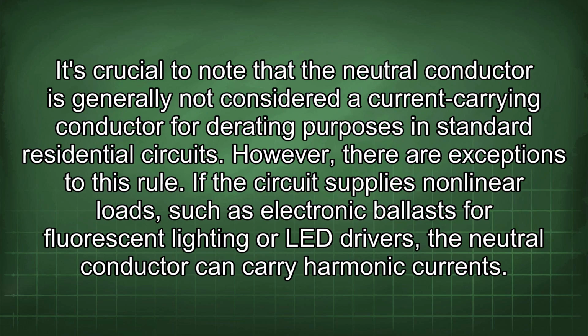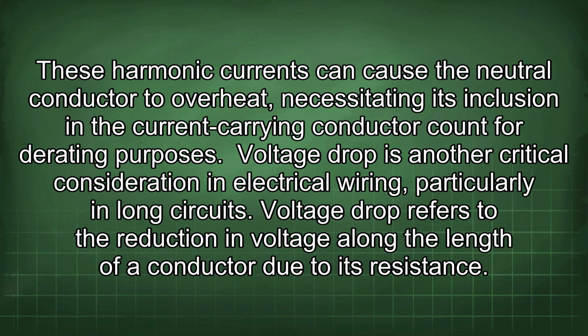It's crucial to note that the neutral conductor is generally not considered a current-carrying conductor for derating purposes in standard residential circuits. However, there are exceptions to this rule. If the circuit supplies nonlinear loads, such as electronic ballasts for fluorescent lighting or LED drivers, the neutral conductor can carry harmonic currents. These harmonic currents can cause the neutral conductor to overheat, necessitating its inclusion in the current-carrying conductor count for derating purposes.